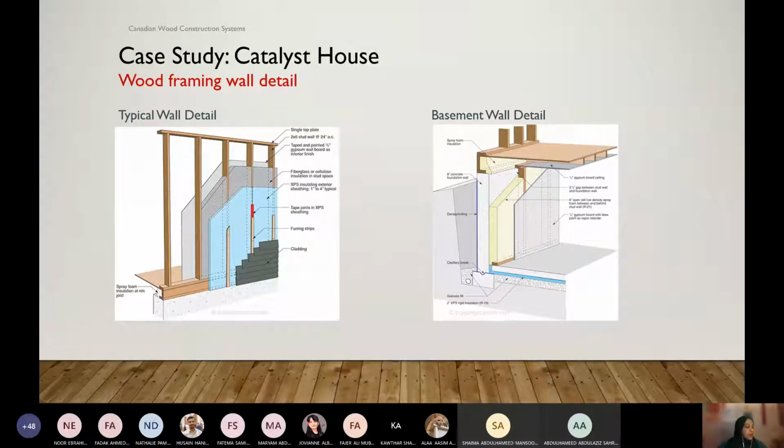So talking about the walls, our systems, that is the standard framing type. But we have very cold temperature outside. We need to maintain warm inside. We have heating, and even with heating or without heating, we need to have a certain temperature maintained inside. So that's why we add some layers in our wall system. It's not just the framing.